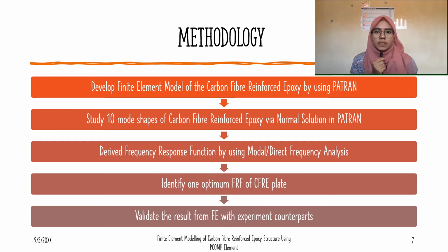The third step is the frequency response function FRF will be derived from modal and direct frequency analysis. The fourth step, only one desired FRF of the composite plate will be identified, and the last step is the result from the FE model will be validated with the experimental counterparts.